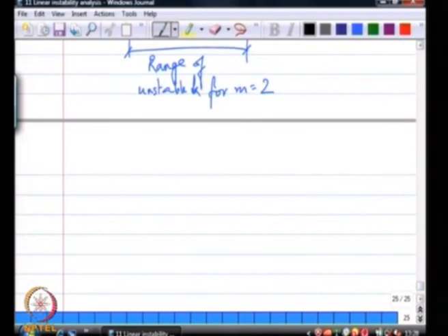So, this is a linear instability analysis of a cylindrical jet in full 3 dimensions. That is what we have looked at thus far. What we will do today is move on to a planar sheet and look at how a planar sheet breaks up. The first example that we looked at was just a single interface of liquid, like air over water. So, what we now want to look at is a liquid sheet of water that is coming out into air, let us say. Okay. All right.